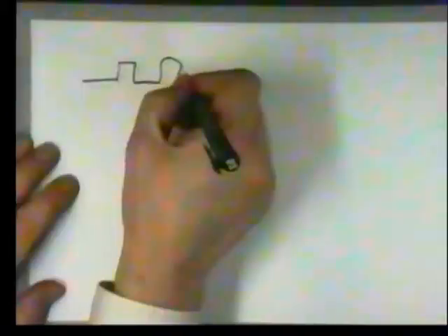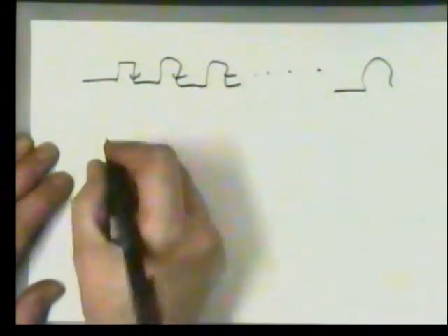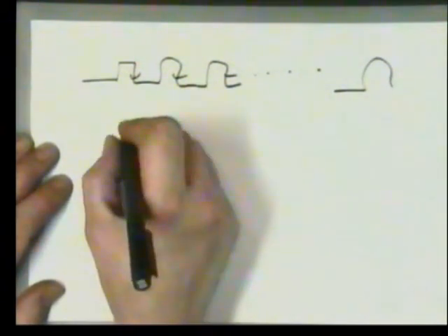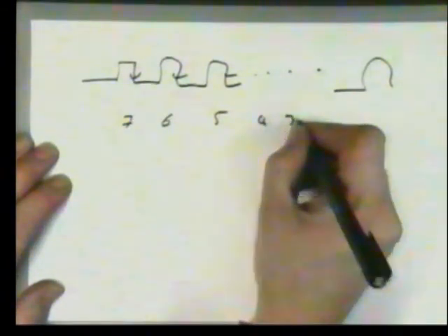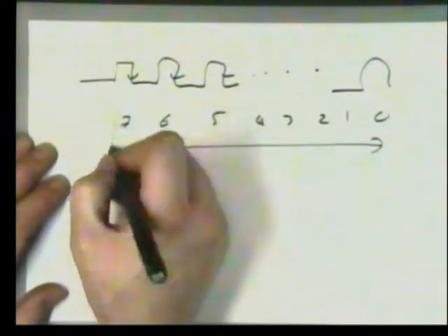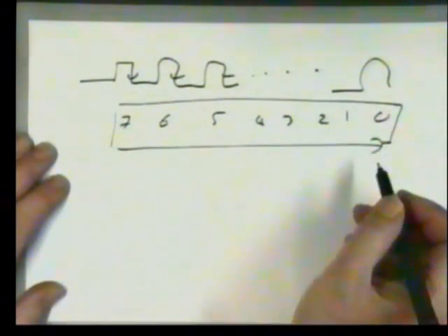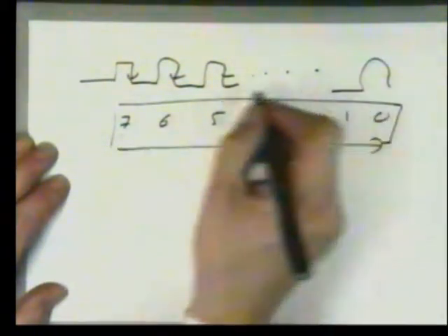Data is also packaged up to be useful, and it's packaged up in bytes. Commands and responses are always byte orientated. So in order to output a command, we have to output 8 bits of data, and it's done most significant bit first. So we do bit 7, 6, 5, 4, 3, 2, 1 and 0 in that order. We clock out 8 bits of data using the bit clocking technique you've just seen, and we always clock out most significant bit first, and it's always in a byte.